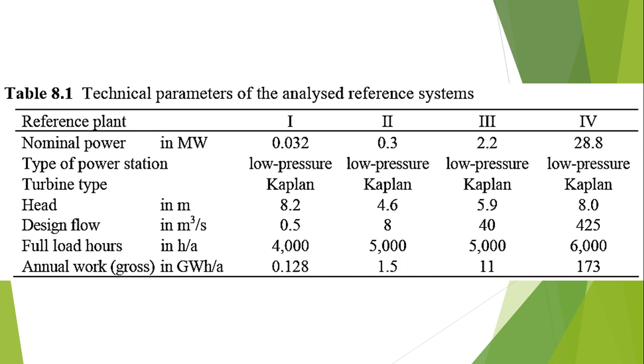The two Kaplan bulb turbines have a combined capacity of 425 cubic meters per second, and the electricity from the synchronous generators is fed into a high voltage grid via two transformers and a metal-clad sulfur hexafluoride switchgear plant.